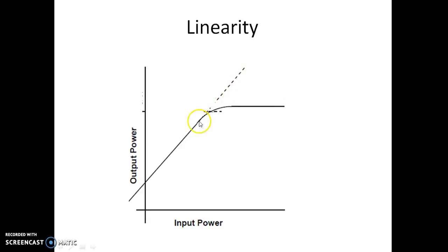But ultimately, what happens is, in the case of RF circuits, or any circuit which involves semiconductor components, the output voltage starts saturating after some level. You can see that as the input voltage increases up to a certain point, the output voltage is also increasing. After some point, it gets saturated, and you have a saturated output voltage for input voltages anything beyond this particular value of input power. We call this saturation.